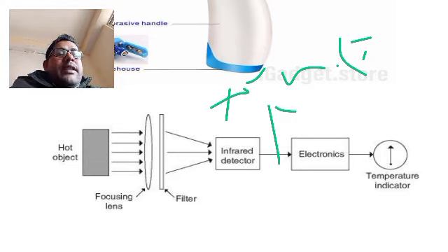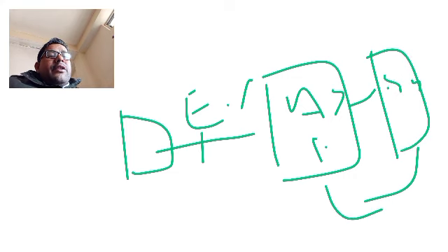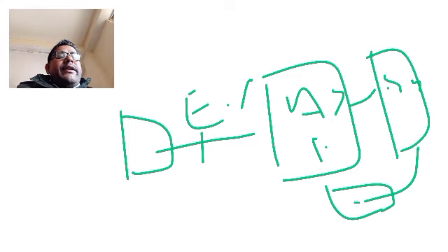so that we can change the signal into a digital signal for display and recording. So in this electronic circuit, so many components we can use. Suppose this is the infrared sensor, the IR sensor output is an electrical form signal. Then we can use one A to D, analog to digital converter. Then we can use a microcontroller or microprocessor. And after that, we can use the digital display recorder. In this way, the process can be done using the digital infrared sensor.